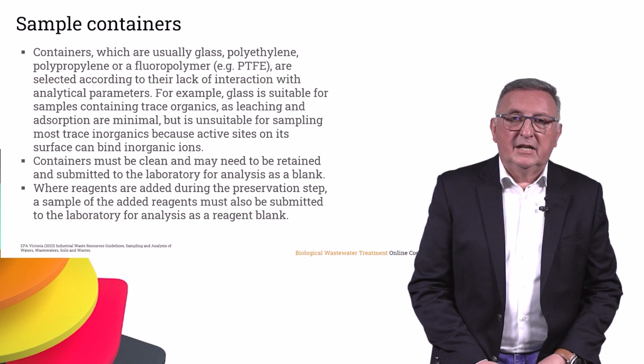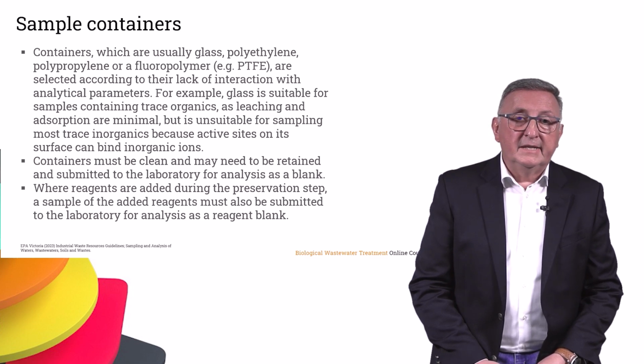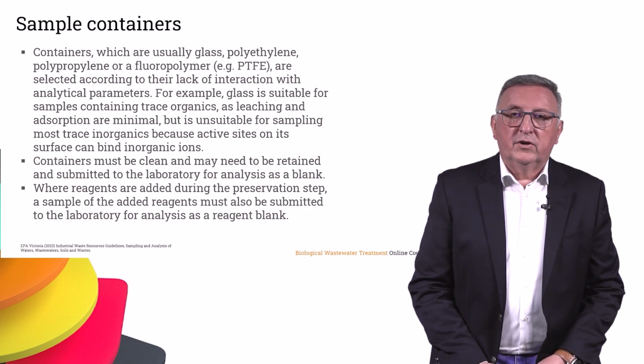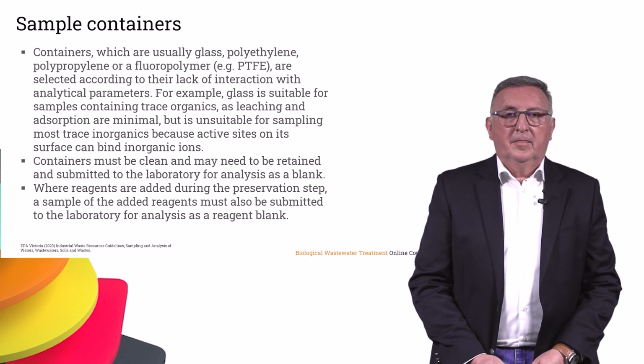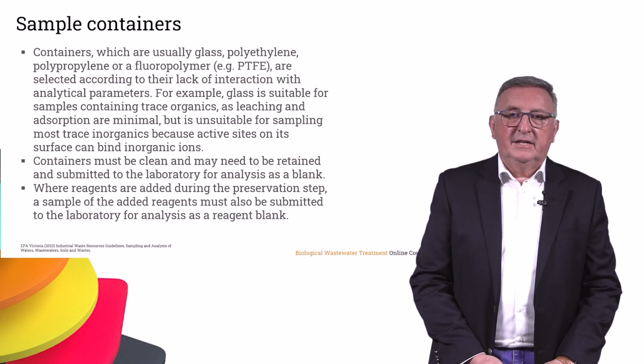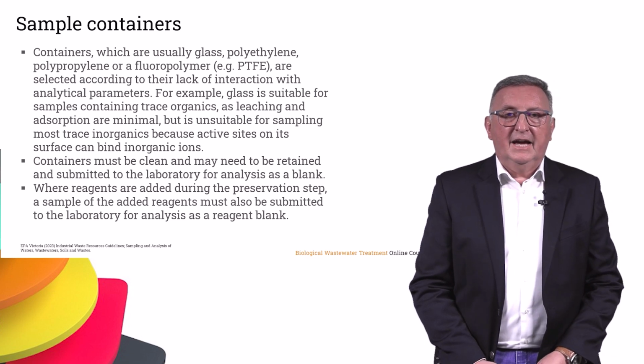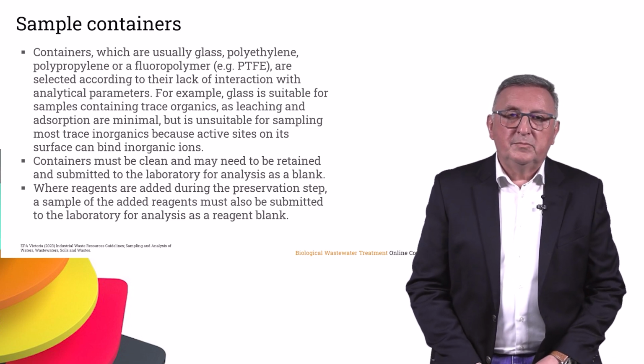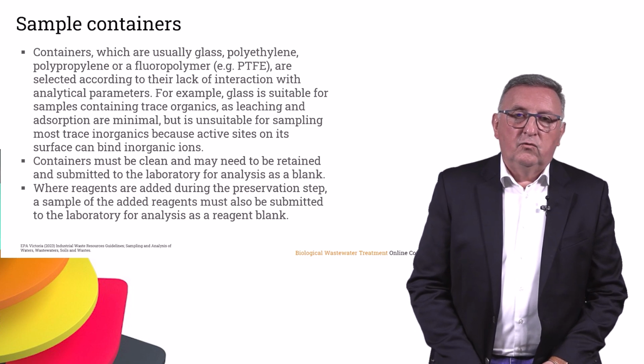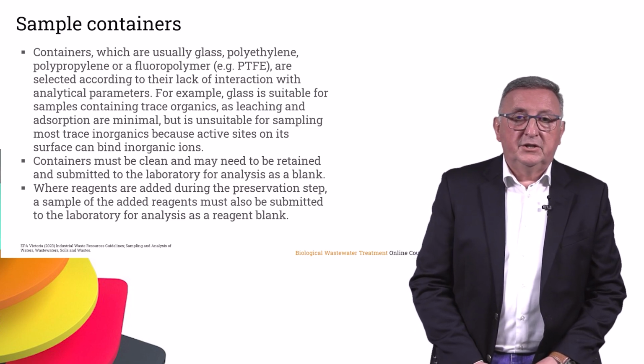Containers must be clean and may need to be retained and submitted to the laboratory for analysis as a blank. Where reagents are added during the preservation step, a sample of the added reagents must also be submitted to the laboratory for analysis as a reagent blank.